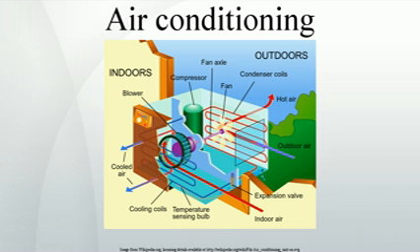Since humans perspire to provide natural cooling by the evaporation of perspiration from the skin, drier air, up to a point, improves the comfort provided. The comfort air conditioner is designed to create a 40% to 60% relative humidity in the occupied space. In food retailing establishments, large open chiller cabinets act as highly effective air dehumidifying units.